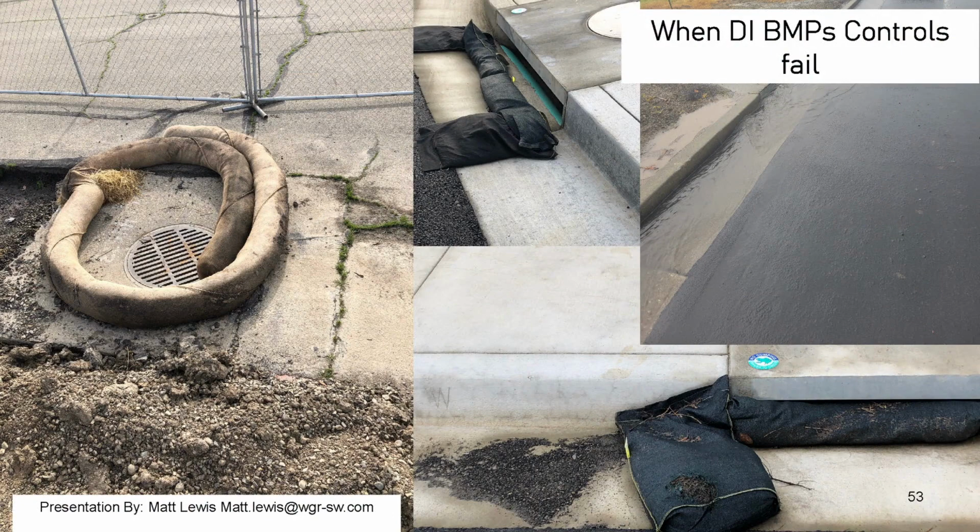And then you have the fiber roll on an impervious surface, on the concrete. So obviously you can't stake it in, you can't key it in, and the water is literally just going to flow right underneath it. And my guy is like, oh, well, what do you mean? I got my DI control. And then I'm like, hey man, come on, come on. And he's like, yeah, okay, you're right. And so they actually put compost sock around it. That's what's on it now, is compost sock.